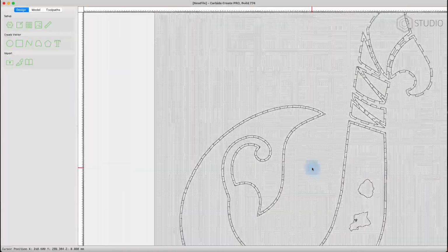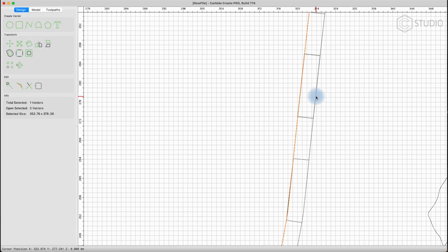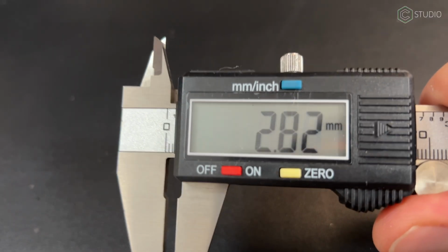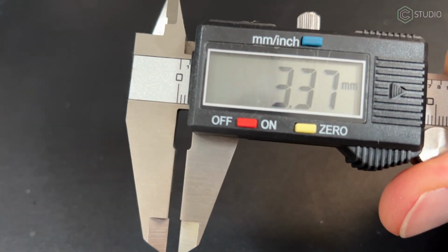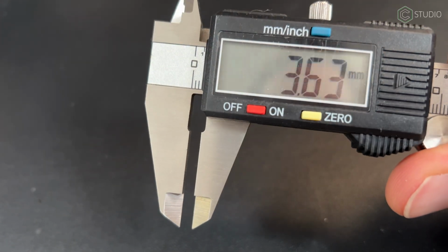But that wasn't enough to make it cut ready. If I cut that outline and pocketed the hash marks, I would still have a sharp, irregular edge. So I created a second outline on each side in order to capture those hash marks as pockets. But what size offset would make a good looking edge? This is where a pair of calipers comes in handy. Visually, what looks like the right amount? What looks strong enough? What looks robust enough without interfering with the design structure or integrity of the logo?